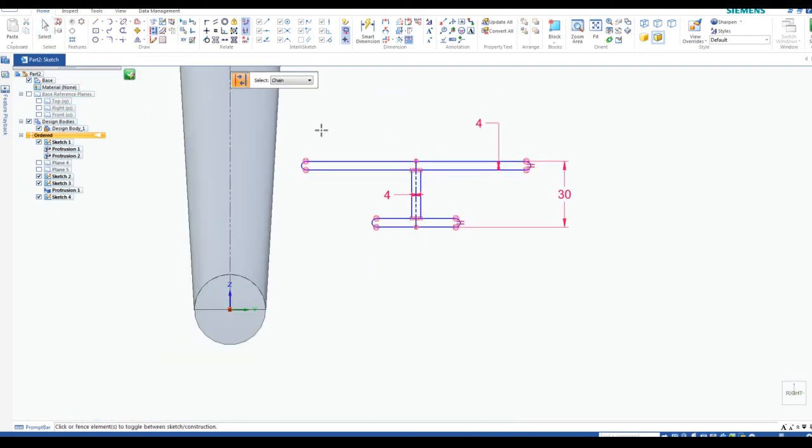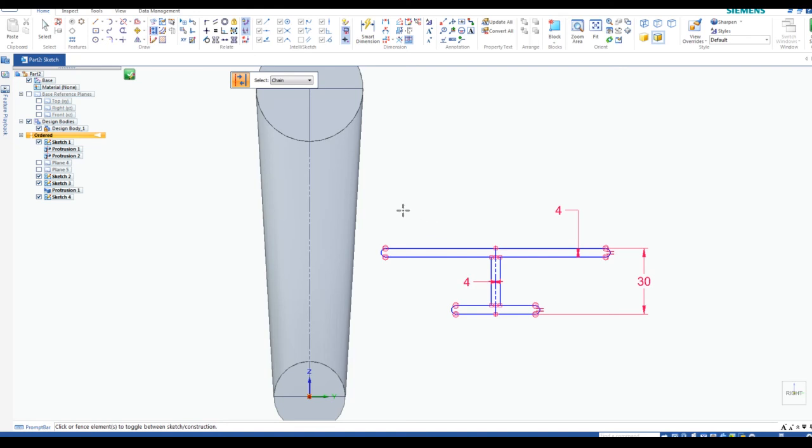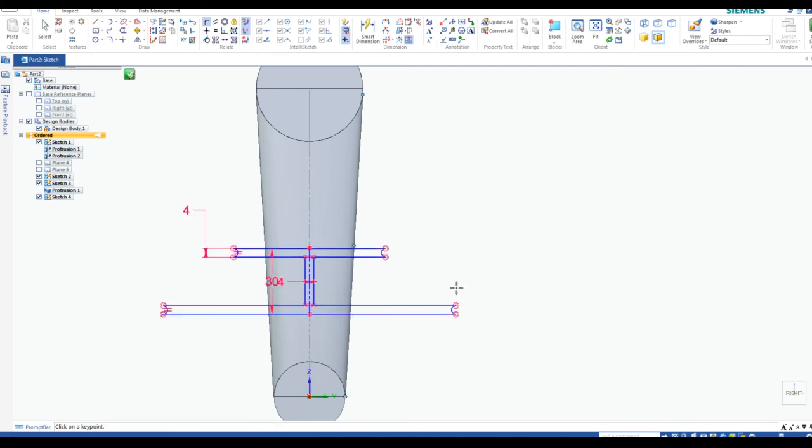The reason is that it is going to line up with this construction line. So let's see if we can do it. First off, I'm going to use my connect, and I'm going to say this point and this line, slams it right in between.